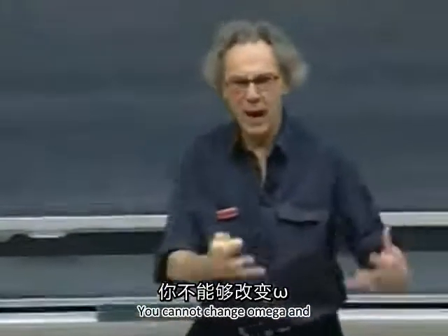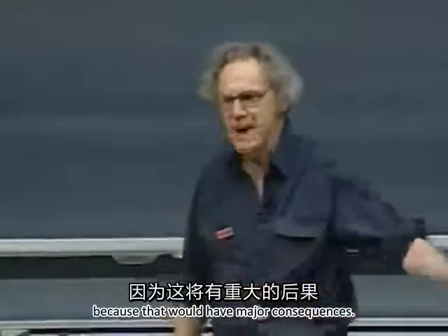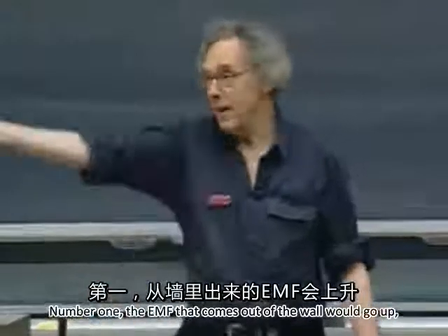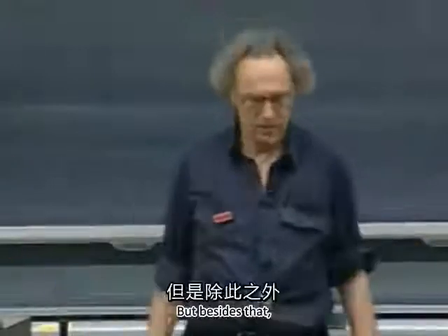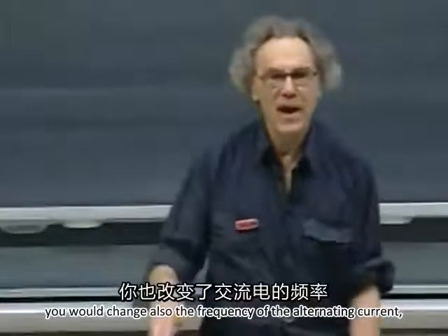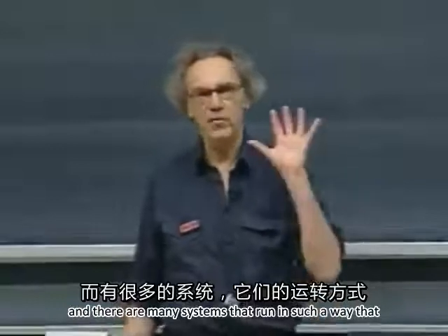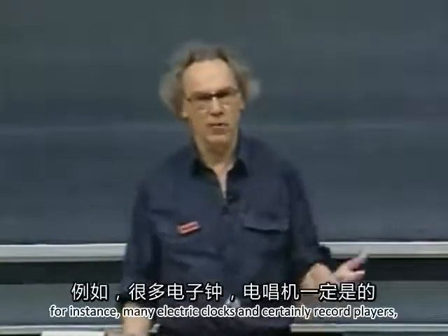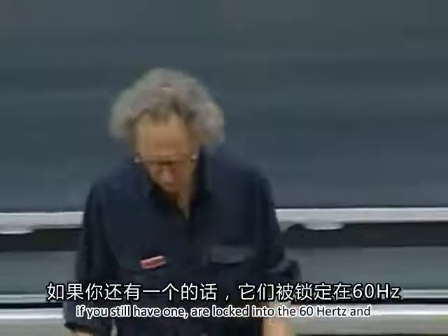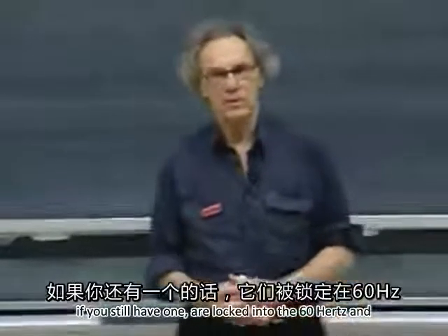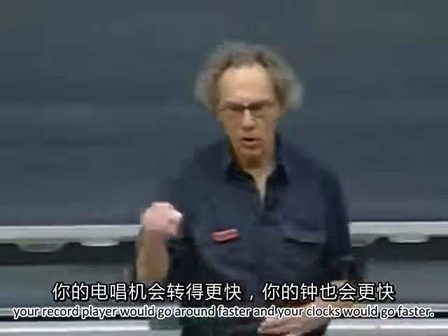You cannot change omega and go faster somewhere where you generate this electricity, because that would have major consequences. Number one, the EMF that comes out of the wall would go up, so you might blow your television, your circuits. But besides that, you would change also the frequency of the alternating current. And there are many systems that run in such a way that they are locked into that frequency. For instance, many electric clocks, and certainly record players, if you still have one, are locked into the 60 Hertz. And so if you were to increase omega, your record player would go around faster, and your clocks would go faster.